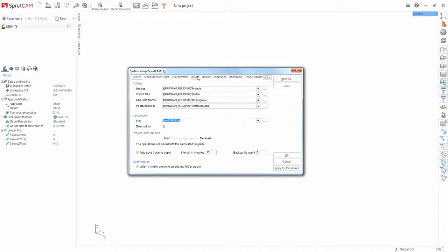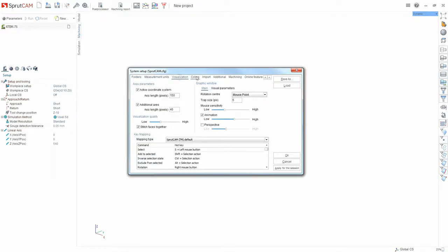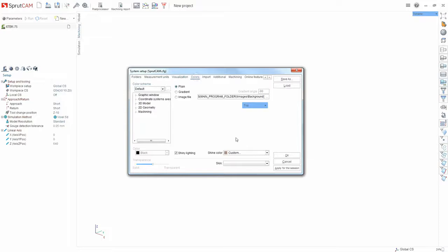Here we can customize the user interface view to fit our needs, as well as the project saving paths, 3D model files, parts blanks, import paths. Also, where the finished project and NC code are saved and where the post-processors that we use are located. There are a lot of tabs and every separate parameter of the system is adjusted. After setup, we can save this configuration in a file, which we can load later.